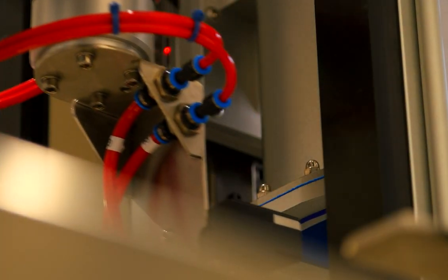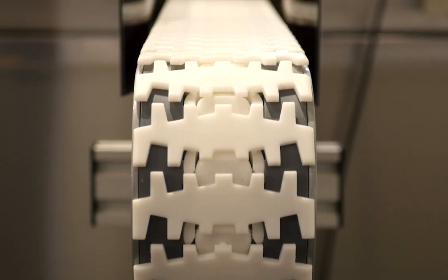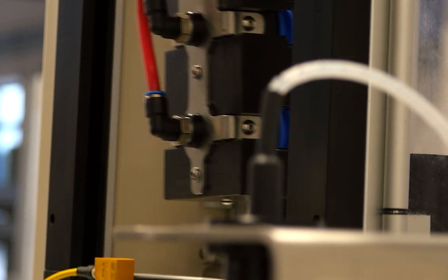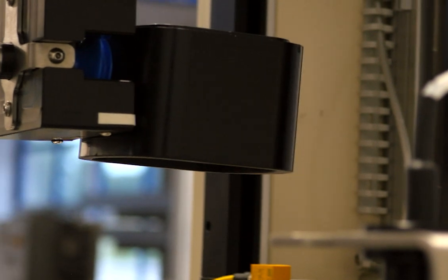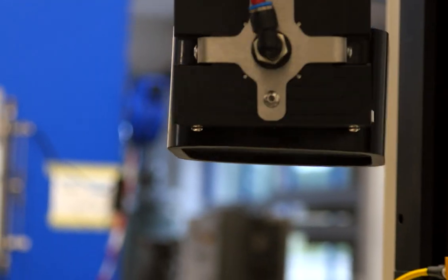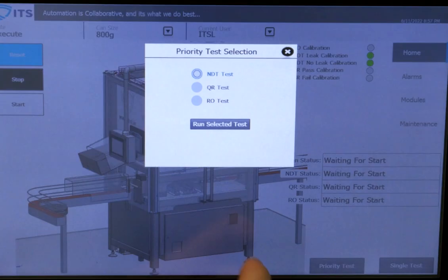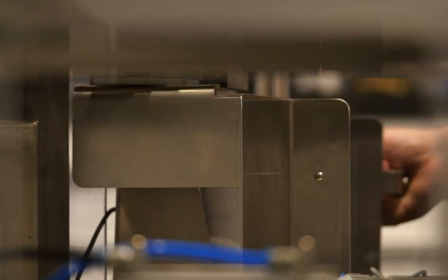This week's application focus is from Cobots.ie in Cork in Ireland. Our partners have created a complete automated testing cell. At the heart of the cell there is a UR5e robot, which is inverted. It has a custom gripper that can pick up the product, present it to a camera so it reads the barcode. It can then present the same part to a different scanner to read a data matrix on the top seal of the part. These two codes have to consolidate together.